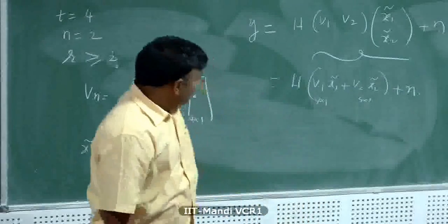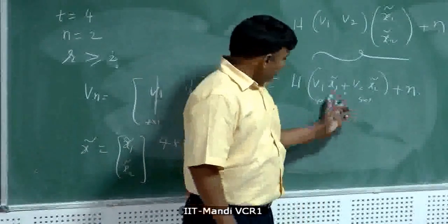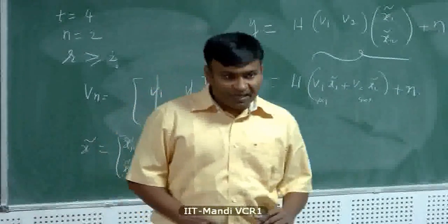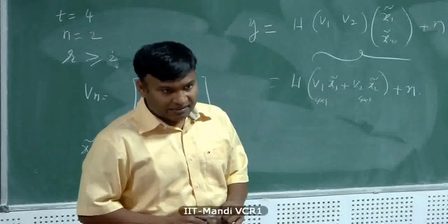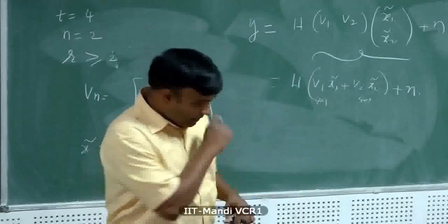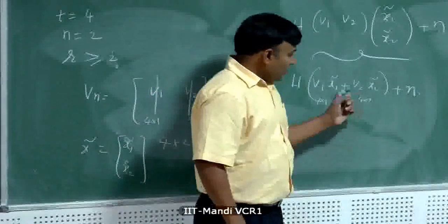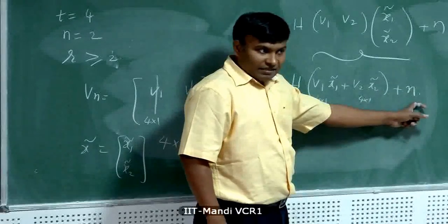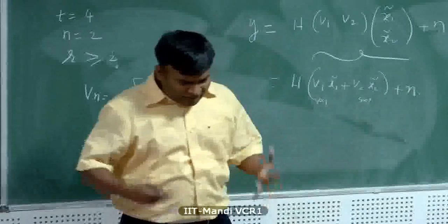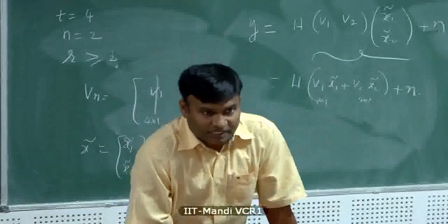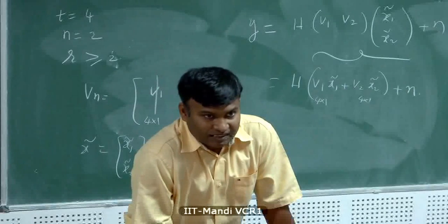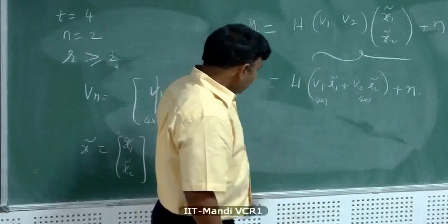But the notion of array gain, when you have a two stream transmission, is a little more complicated. You can't put an exact number on it. It depends on the number of receive antennas as well as the number of transmit antennas, and you don't get this perfect array combining in multi-stream transmission. I think you should simulate and see it. You don't get this perfect array gain in multi-stream transmission.